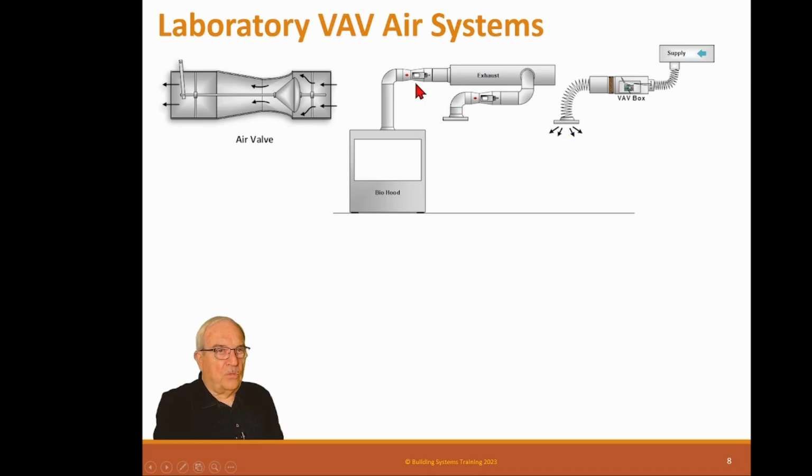Now, some people have tried to make this exhaust system follow the supply by offset, and these two still work together. You can do that. It's very complicated, very difficult to get set right and to keep right.